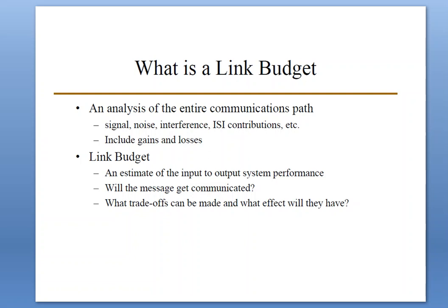What is the link budget? It is an analysis of the entire communication path. It is not about a specific channel, a specific transmitter or a receiver. It is an analysis of signal, interference, ISI contributions, etc. It also includes gains and losses produced by the transmitter as well as the receiver.